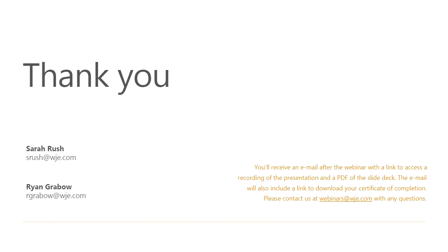All right, this is a historic question. When did flashing become commonly used? Many historic structures do not have flashing. Sure, I can take this one. And I'm seeing this a little bit in questions throughout the Q&A section. Flashings are more meant for drainage systems. So when you are intending to have a drainage cavity, and you're exactly right, historic systems like mass masonry don't have that cavity. They're meant to breathe.